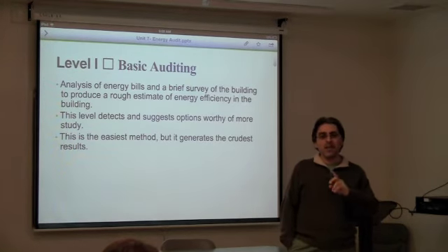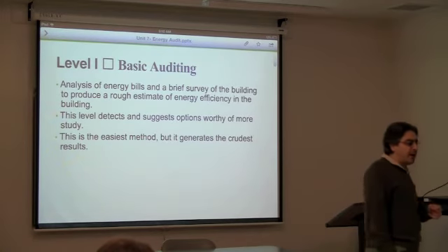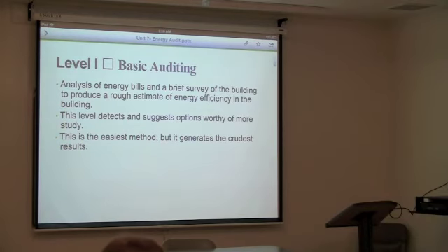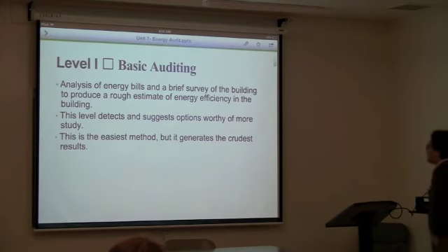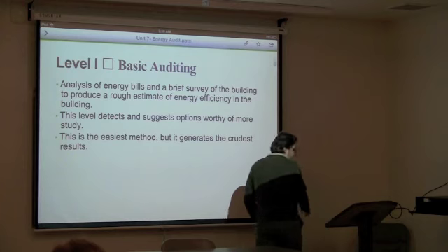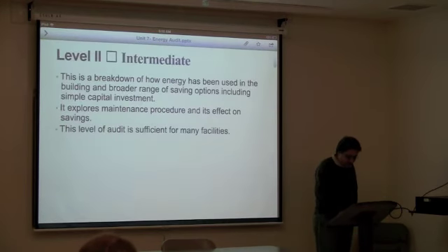I'm not talking about the main meter that the gas company is running. If you look at, for example, a refinery, there are maybe hundreds of different meters inside the refinery that are local, internal to the usage of each unit. Each boiler has its own meter. That's how you measure the energy usage for each boiler, right? So by having the pattern, you establish that your reading is correct, and you also try to make that pattern for each meter.